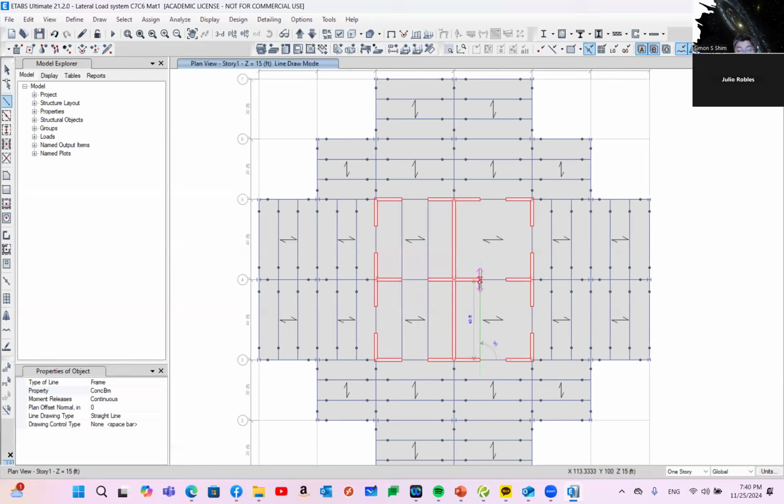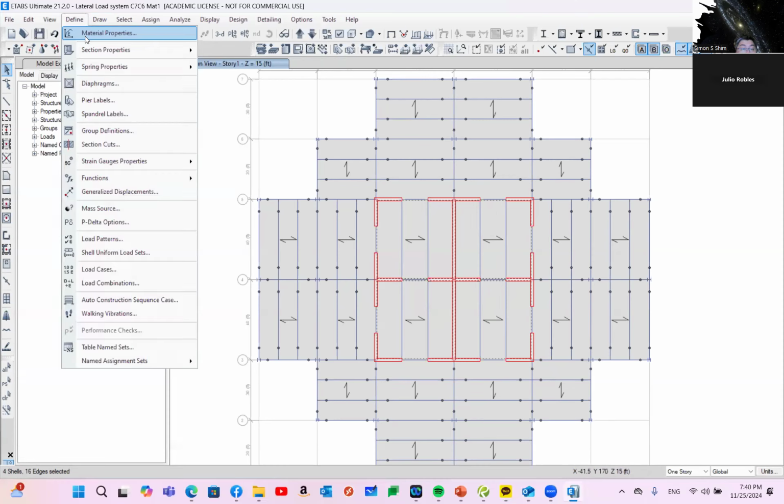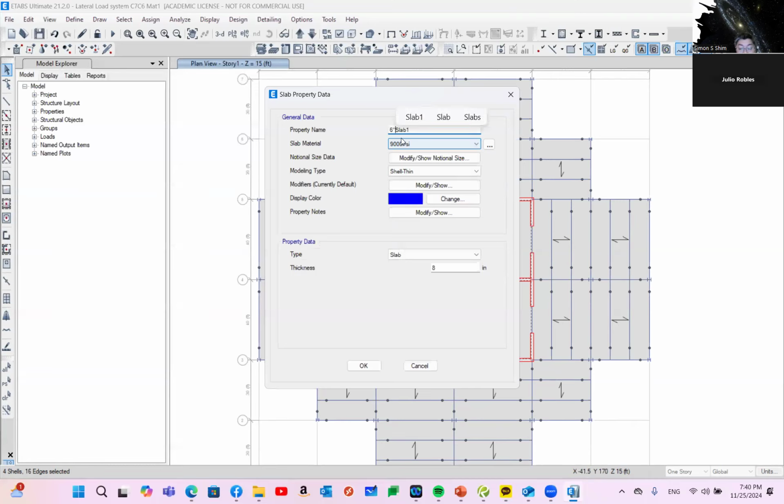Okay, we're going to use a one-way slab like this, and this one's not going to be the metal deck slab. This is a concrete slab, but you're not focusing on this. Let's say I'm going to assume a 6 inch slab is typical. So 6 inches. We can use a membrane, so no contribution. Use a special load distribution.